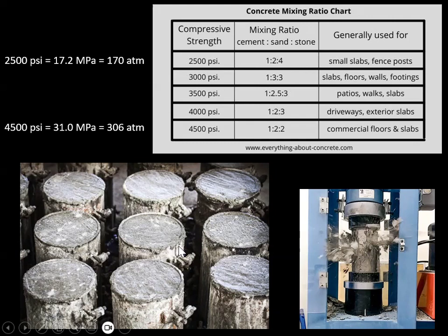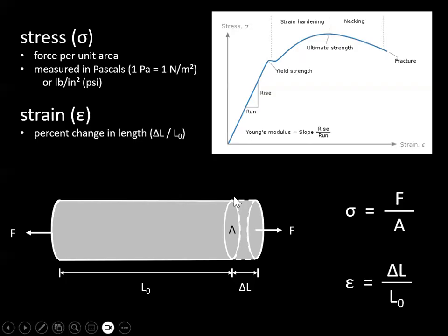Now, if I run my calculator, let's do 4 inches diameter, square that times pi over 4. That's a cross-sectional area of, let's call it, 12.5 square inches. You guys see that? Then if you put some force on it, however many pounds that is, divided by about 12.5 square inches, you can determine the stress, right? Because force over area, stress is like a pressure. That leads to this right here.